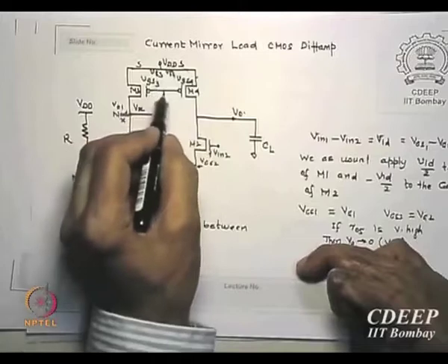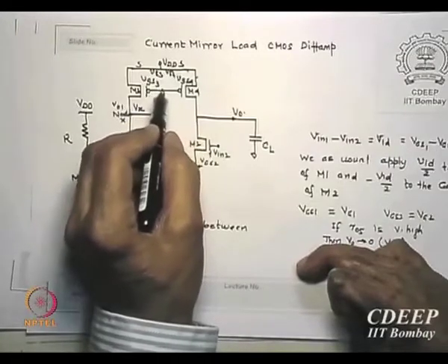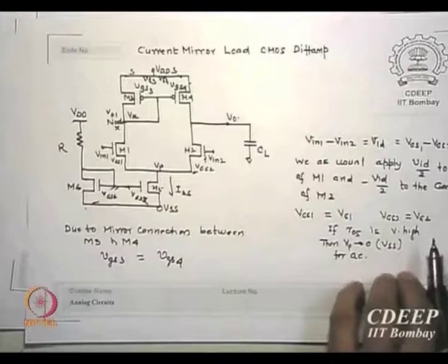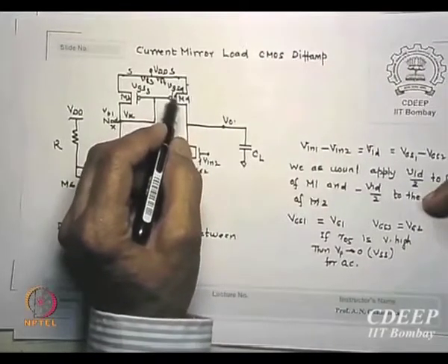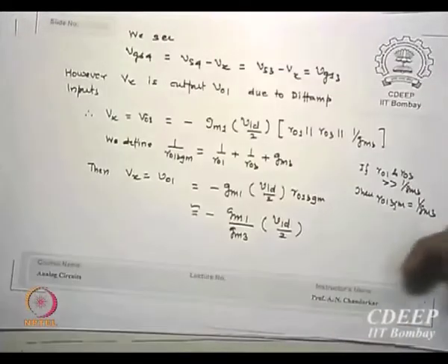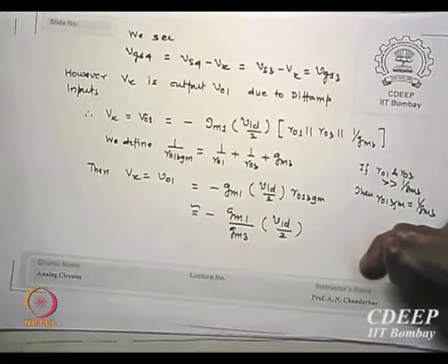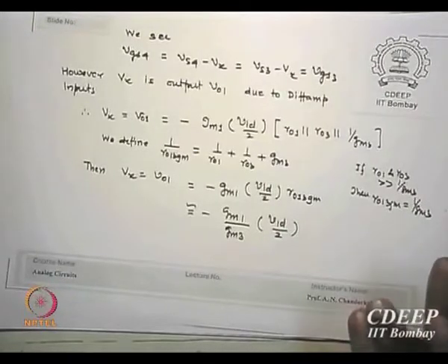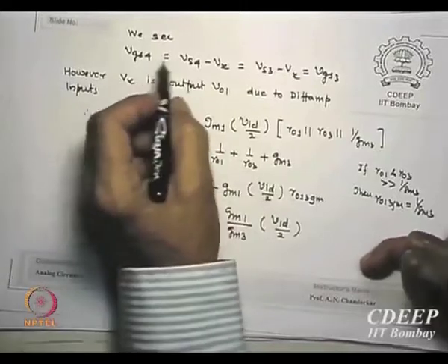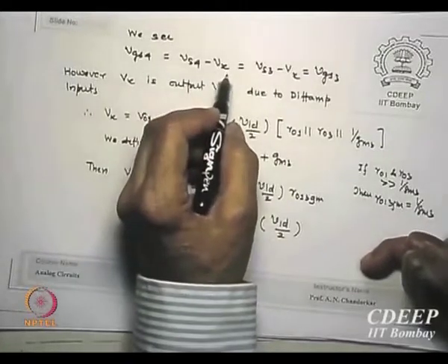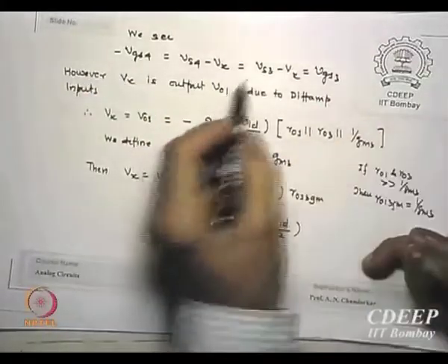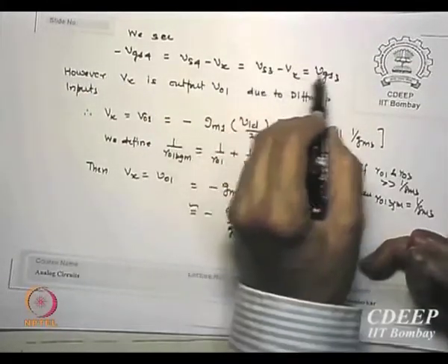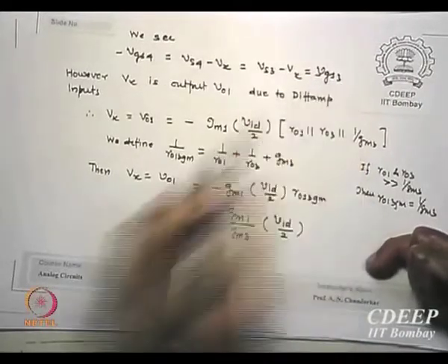Source. So this is, or rather Vx minus this equivalently saying, okay. Vx minus Vs is VGS, yeah, that is what I wrote. No, that is because it is a P channel device, a minus potential will appear, okay. So we say VGS4 is VS4 minus Vx, okay, you can also call it minus, fair enough. This is VS3 minus Vx.